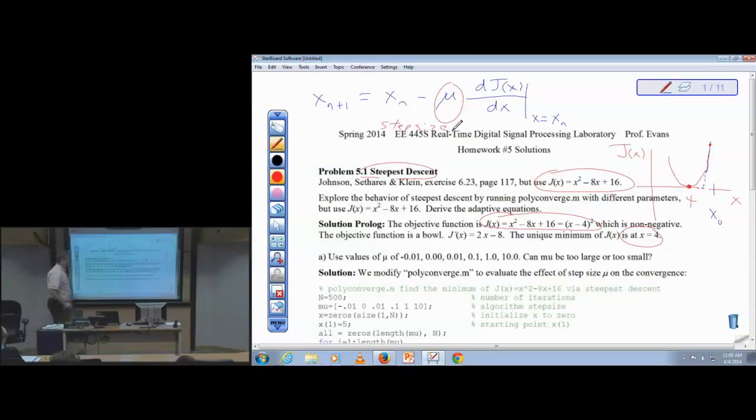So we don't want to go the whole way. We'll go some of the way, and we'll control it by mu. And so in practice, a common value of mu for equalizers and lots of other systems is about 0.01, very common, and I've seen as low as 0.001. So we tend to use a very small mu to take small steps downhill in this case.